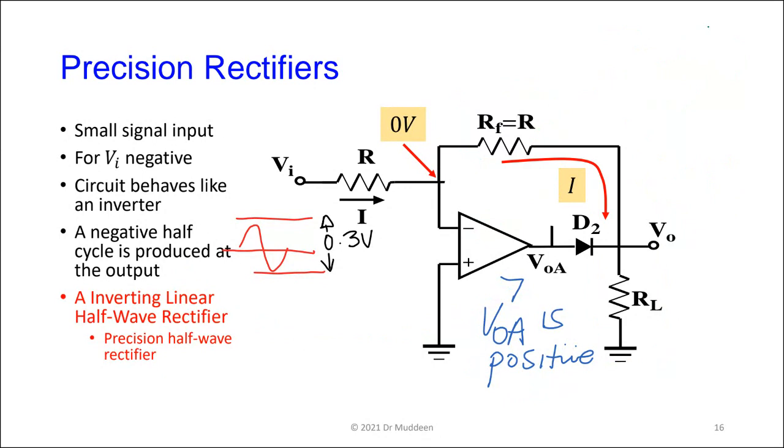It's an amplifier, but of course we have negative voltages coming in, and because of the behavior of the output here, this has to be positive with respect to that, but this is at ground, so the only way this could remain forward biased is if here is more negative than here, or here more positive than here, however you want to put it. This is at 0, so here clearly has to be more negative than it, so the output is a negative voltage at that point. So what you get coming out is that.